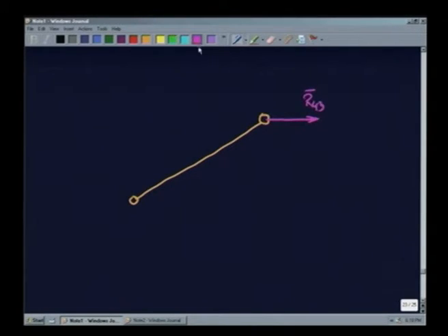We also know there is no other external force, but it is under the action of the inertia force FI3 and an inertia moment MI3, and there is a force here we have to find out. This point was B, this point is A. Now, our job is to find out the last force which is still unknown on this.